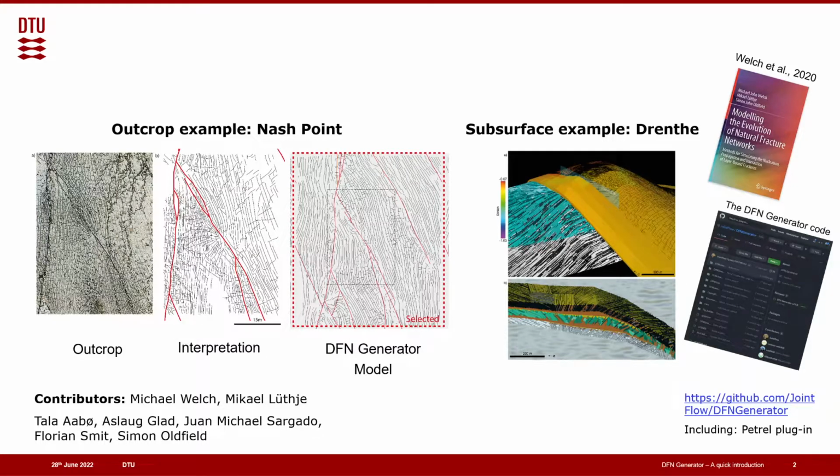Over on the right-hand side over here, we can then actually see that we've inserted the red lines, the faults, as controls, and then we've simulated the strain distribution and fracture growth around those. And we believe that this provides a reasonable comparison or reasonable representation of the fractures in a digital form.